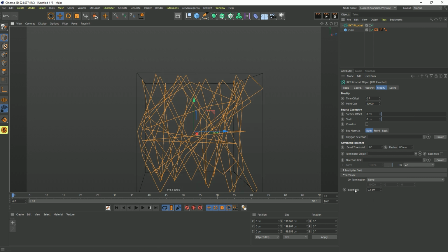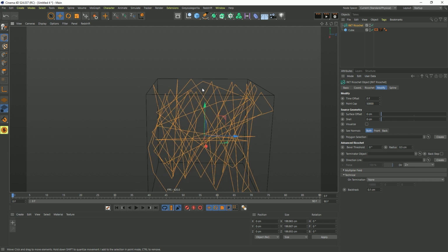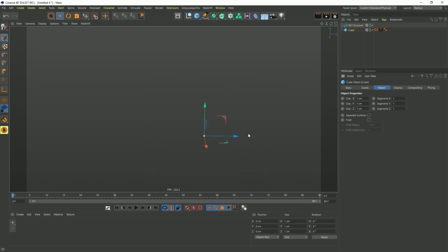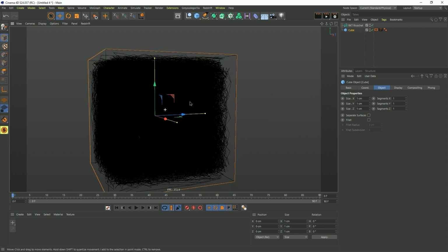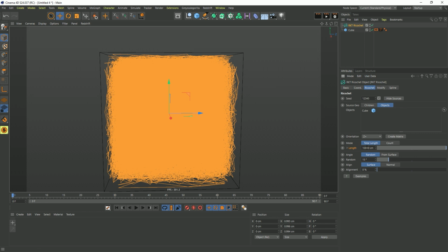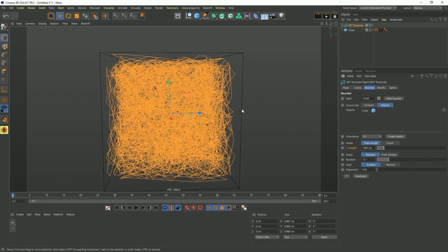Now, our default value here is 0.01, which is really small, and you really won't be able to tell the difference. 99.9% of the time, you'll never need to think about the setting or ever change it. But if you're working in a very, very small scene, so let's say that this cube is only 1 by 1 by 1, it gets really, really tiny. So hit the letter S to zoom up on it. And now the Ricochet is going a lot further because it's a total length, and this is now way smaller. So I'll divide that by 10. You can see we're getting all those bounces.